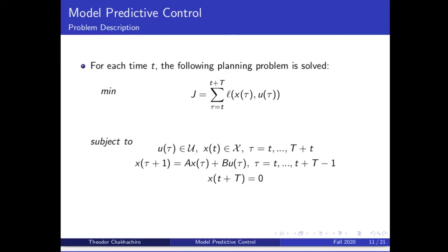For example, in a robot motion planning algorithm, we can plan for 10 initially, move one step further in time, then replan for 10 steps forward. So actually relaxing the constraints if you want to think about it. We are not only considering 9 steps once we move one, we are also replanning for 10.